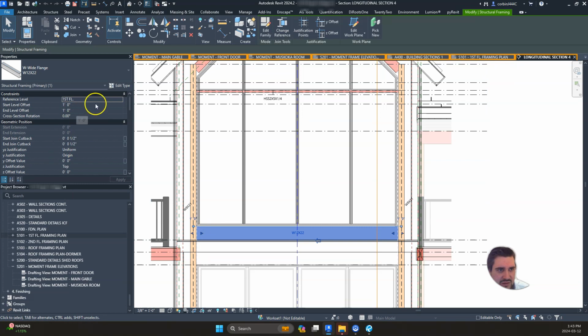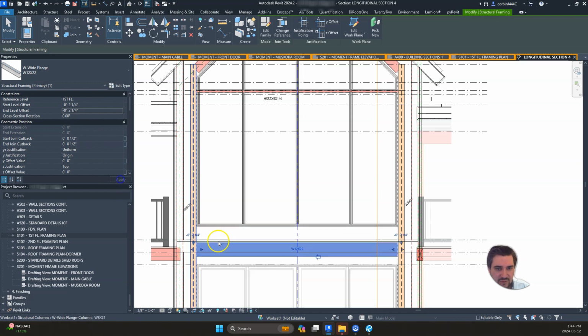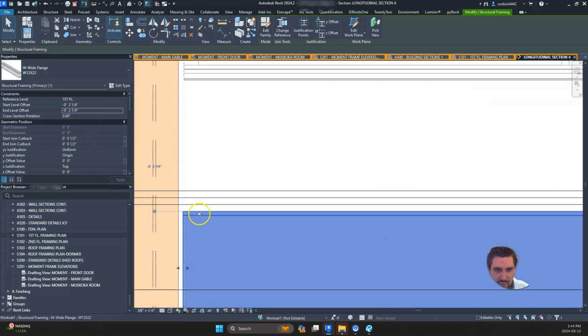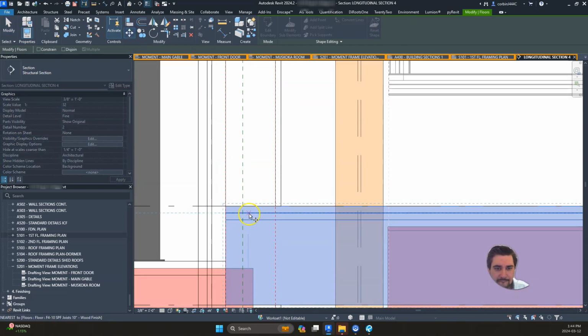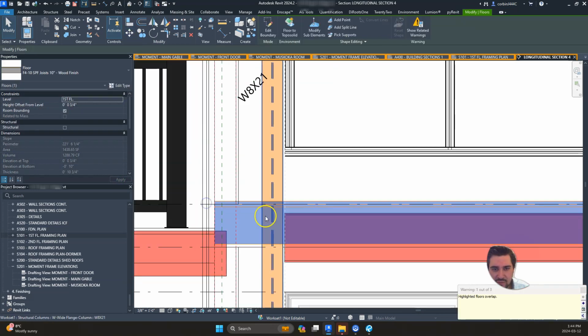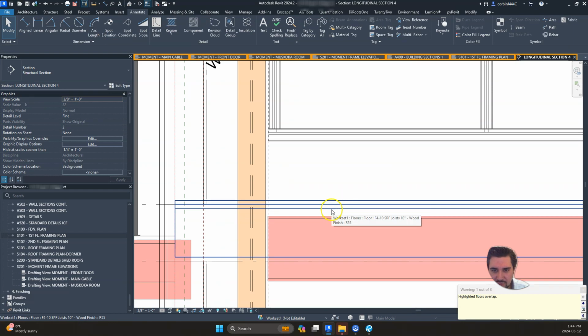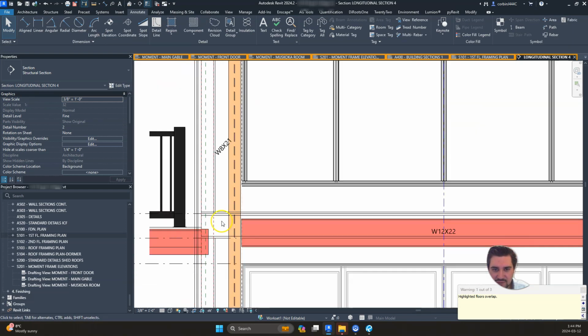So we're going to lower this to be negative, it'll probably be negative 2.25 inches. So that's basically 1.5 inches below our subfloor. Subfloor should be up there, so that's our floor finish. We have our subfloor. Now we have 1.5 inches of space in there.